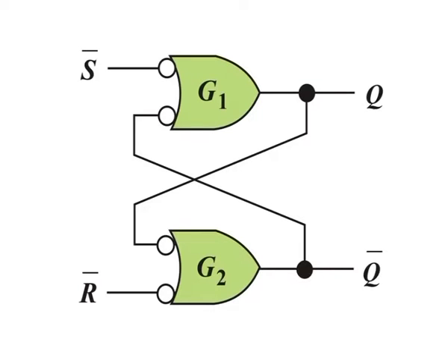In normal operation, the outputs of the latch are always complements of each other. That is, when Q is high, Q bar is low, and when Q is low, Q bar is high. An invalid condition in the operation of an active low input SR latch occurs when lows are applied to both S bar and R bar at the same time. As long as the low levels are simultaneously held on the inputs, both the Q and the Q bar outputs are forced high, thus violating the basic complementary operation of the outputs.